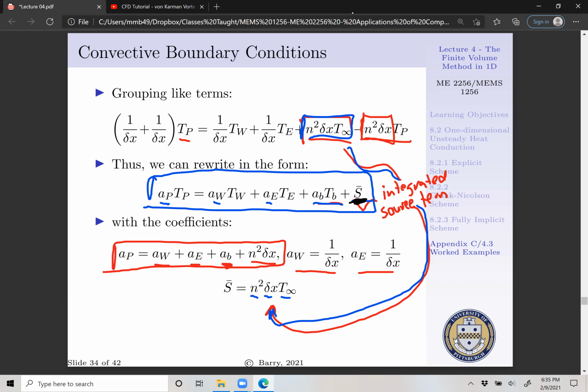We've covered non-uniform grids, we covered source terms, we covered transient analyses. The only thing we'd have to do is cover temperature-dependent material properties, and a little bit of multiphysics. But multiphysics in and of itself is just a source term. So we will look at how that's done. I think what's going to be really fun is we'll try and do an example of a conductor that has temperature-dependent diffusivity, temperature-dependent electrical resistivity, and is carrying a current, and look at how those temperatures evolve, assuming a uniform current density is flowing through it. And just how we set up an iterative algorithm to handle temperature dependence.